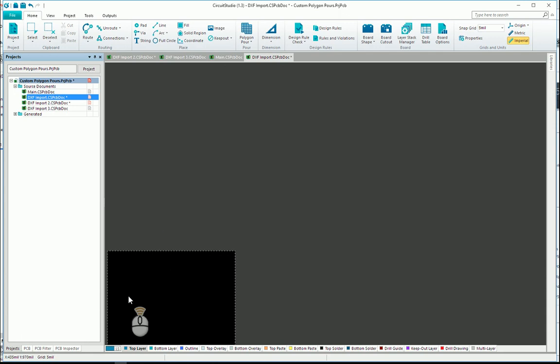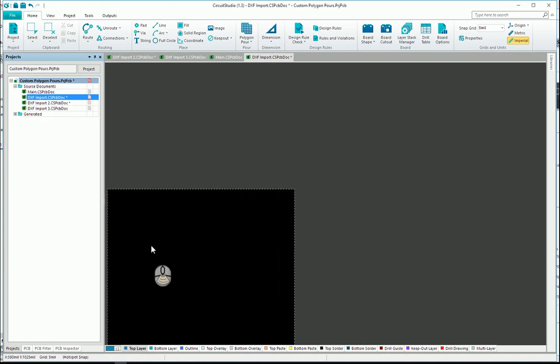It's also a good way to organize your project. If you have lots of polygon pours, I just recently completed a project with probably 150 custom polygon pours, so it was vital that I kept everything organized. So I'm going to show you the workflow, which doesn't take long to get, and the little details of moving DXFs in and making polygon pours from text and such.